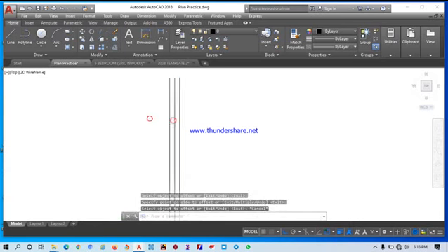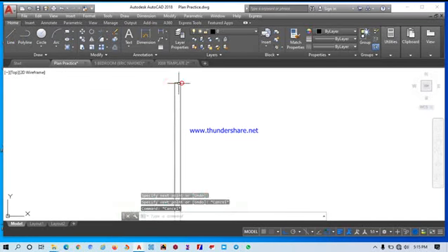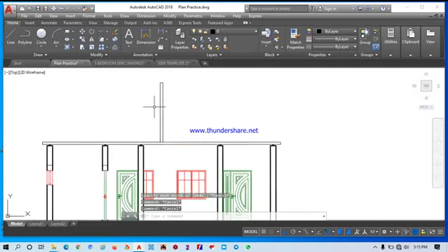That's good. So now delete the center point. It's just for precision, so that your king post is the one at the center of that building, of your roof trusses, where the other members are hanging on.